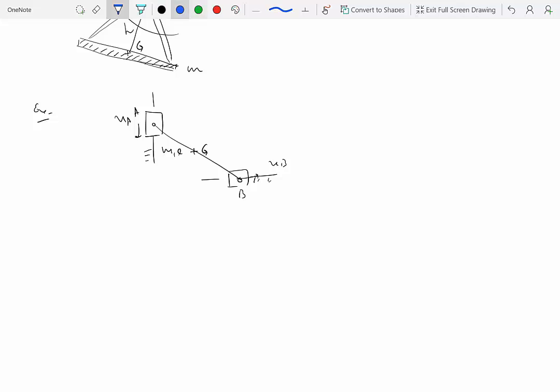We're looking for the kinetic energy at this particular instant only, because at a different instant the kinetic energy may be different. We can, of course, write the general expression, which says 1/2 m v_G squared plus 1/2 I_G omega squared, but you can locate the instantaneous center of zero velocity, about which this rigid body, this rod, is momentarily rotating, and treat that instantaneous center as a fixed point. So the first thing is we have to locate where that instantaneous center is.